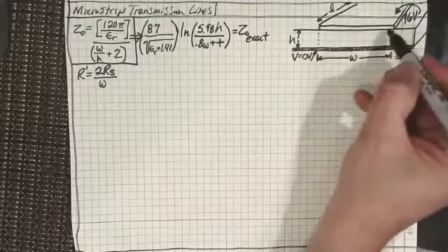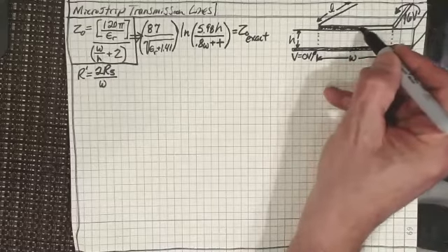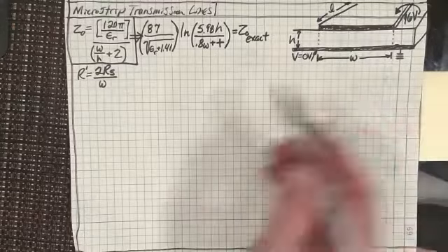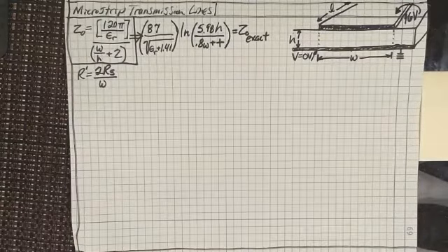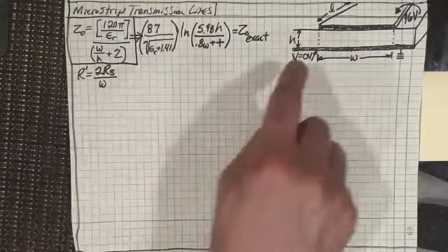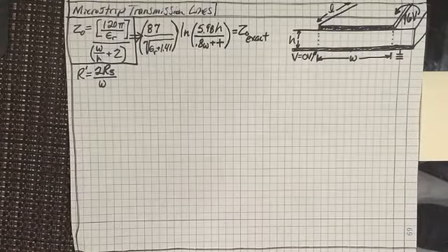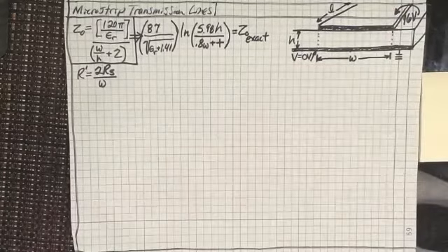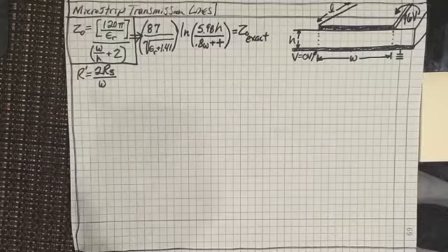And then we've also got a line up here too that also is made out of copper, and it's a certain width. And in fact, the width that we've got and the height play a big part in what the characteristic impedance of this communication line is going to be. Now, you probably see that I've got 16 volts on the top and I've got 0 volts on the bottom. It doesn't really matter what the voltage differential is. I just wanted to show you that there was an electric field across.